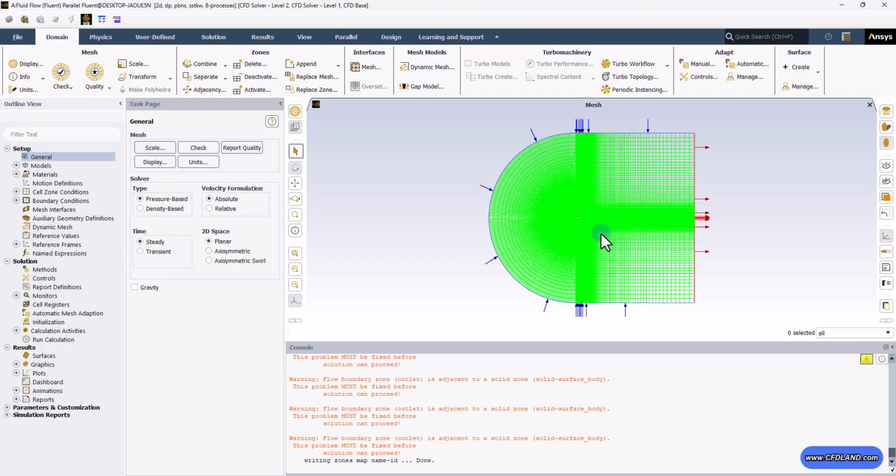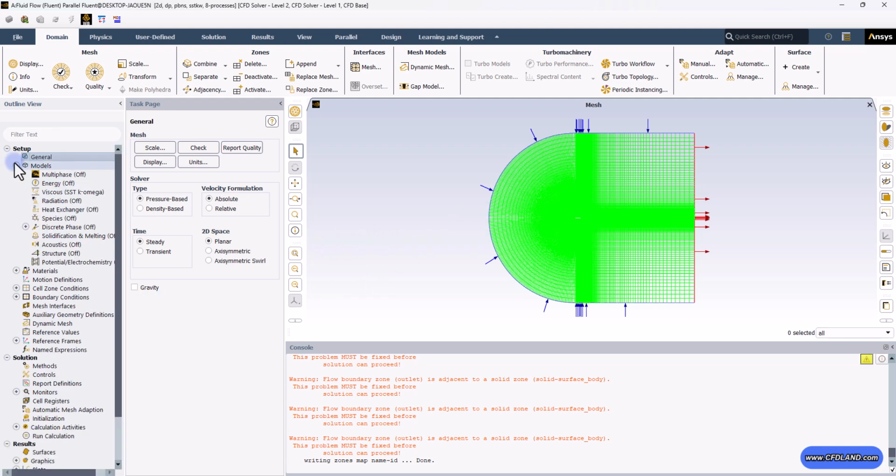Then it comes the time mode. We want to investigate the performance of the airfoil as soon as it reaches the steady-state, time-independent condition. So we do not need to change it. And finally, we actually do not want to consider the gravitational acceleration effect in this aerodynamic analysis.